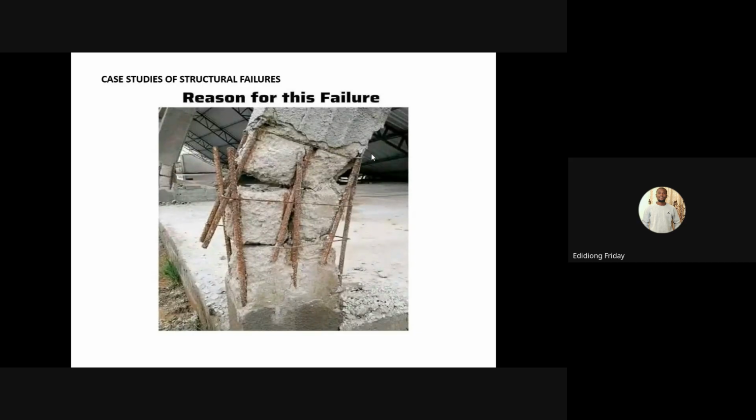stirrups. You can see the kind of tiny stirrups. This is maybe even less than Y8. You can see how tiny it is, and it's obviously inadequate. This is a joint and needs as much shear reinforcement as possible, which are the links or stirrups. And you can see how tiny they are, and look at how they are spaced.